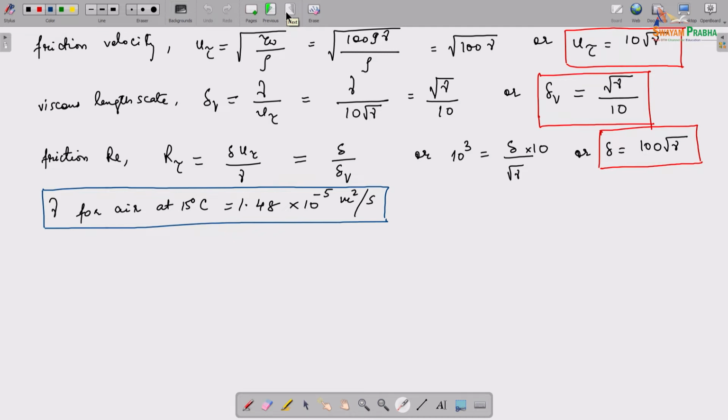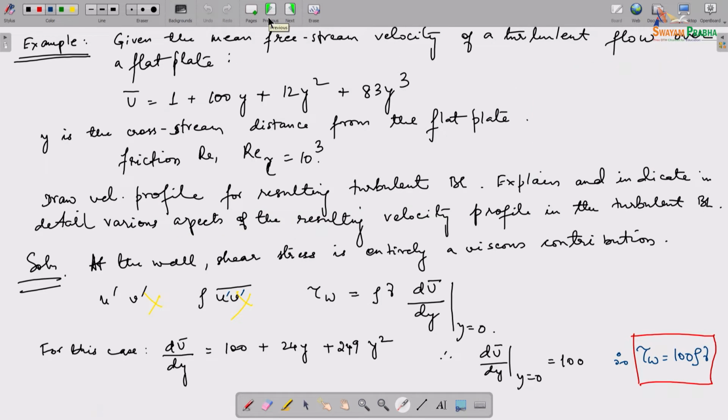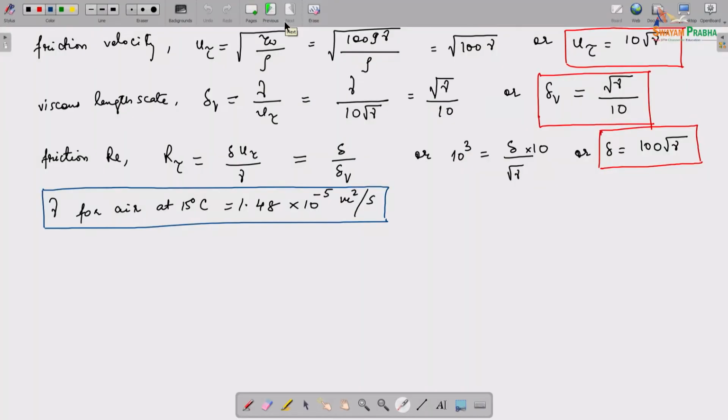Then now, what exactly are we talking about when I say friction Reynolds number and things like that, right? So, this is from the law of the wall, and we know that right near the wall there is this length scale which is governed by scales which are independent of the free stream velocity and density of the fluid, right. So, we can therefore develop exclusive length scales for that, which is what we are doing here, okay.